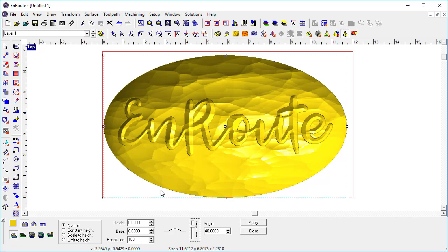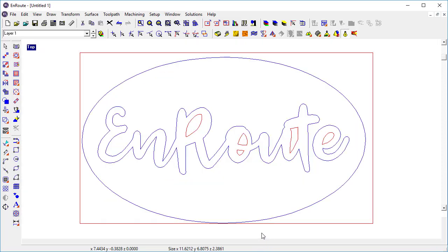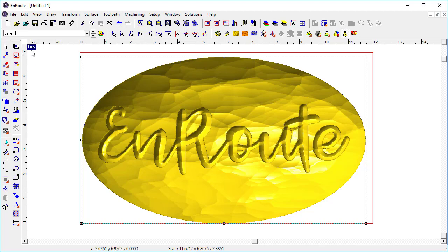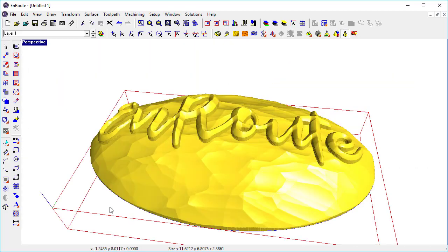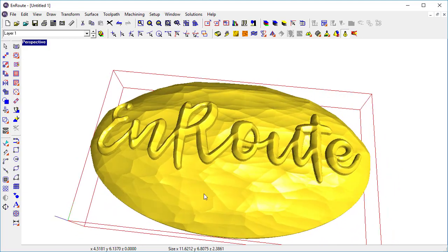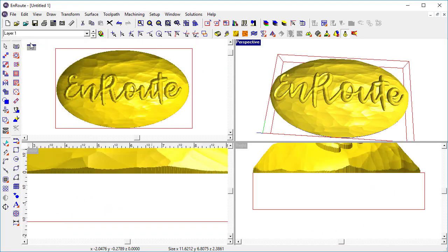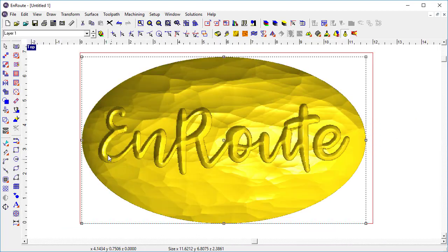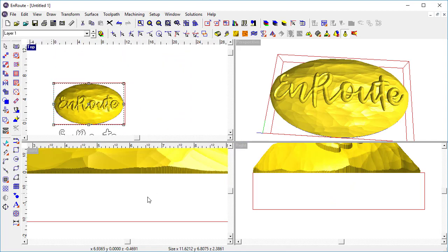And so in this case I've got beveled, and I'm going to add some rounded to it, and so this gives me kind of the look I'm looking for. So now if I flip here, you can see that I've got a surface that is, I think, an interesting surface that took me just a couple of minutes to create. So now if I want to toolpath it, then I'm going to move it down into the material, and